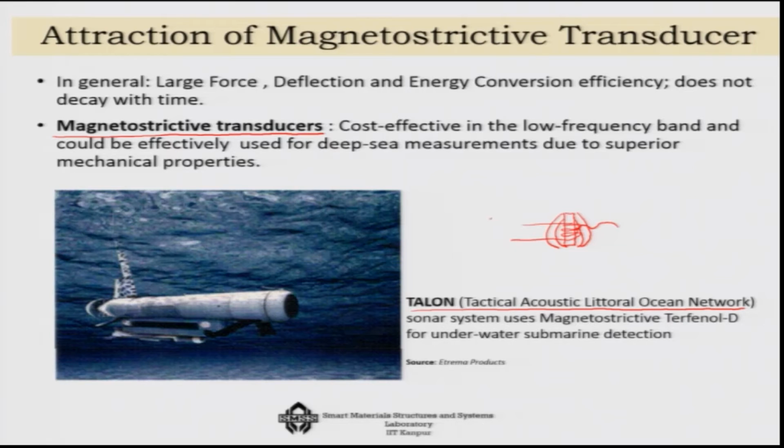If this pickup coil is attached to a signal analyzer, you will see the signal change. You will see, in the time domain, the current change, or you can convert it to an equivalent voltage change, and you can see that there is a wave or a vibration coming up in the system. Thus, you can develop a transducer using magnetostrictive materials.